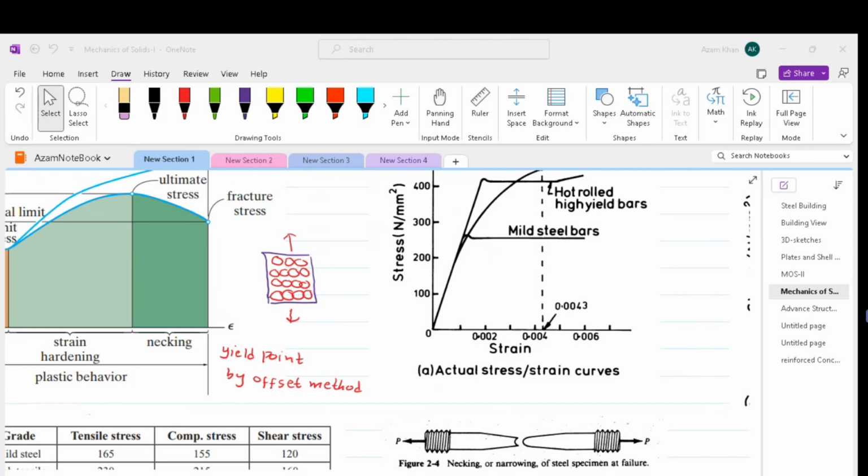In the case of necking, the material stretches very rapidly and simultaneously narrows down. Thus, the rupture load is actually distributed over a smaller area. If the rupture area is measured after the failure occurs and divided into rupture load, the result is a true value of actual failure stress, although this is considered considerably higher than the ultimate strength. Nevertheless, we don't consider the rupture stress, we consider the ultimate stress as the maximum stress.